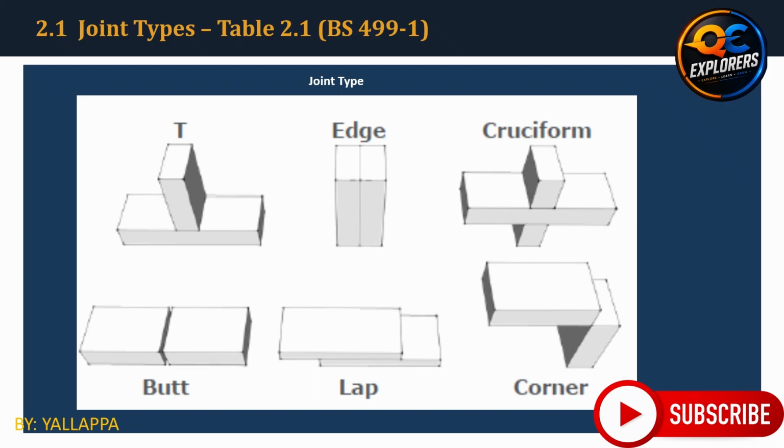A cruciform joint is formed at right angles. The components intersect to produce a cross-shaped arrangement. Finally, the lap joint involves overlapping components, with the relevant configuration falling within the 0 to 5 degree range. For examination purposes, the angle ranges are worth learning accurately. But do not rely on the numbers alone. Associate each range with a physical picture.